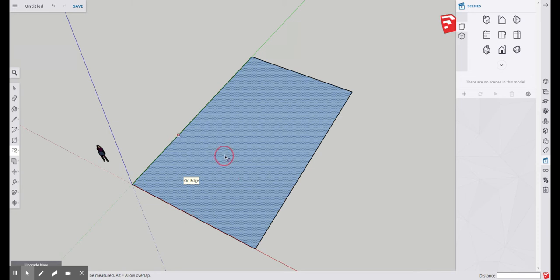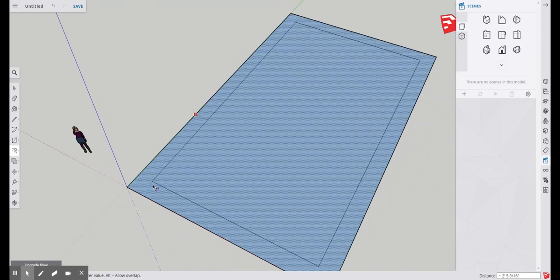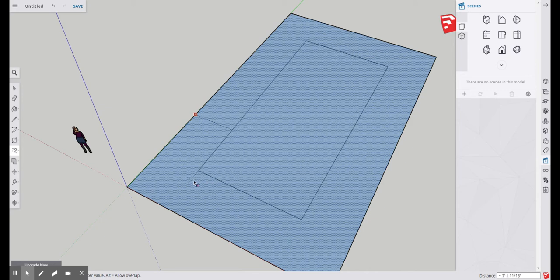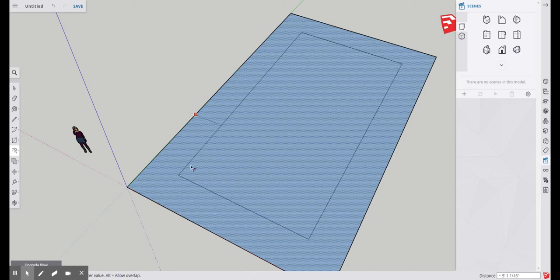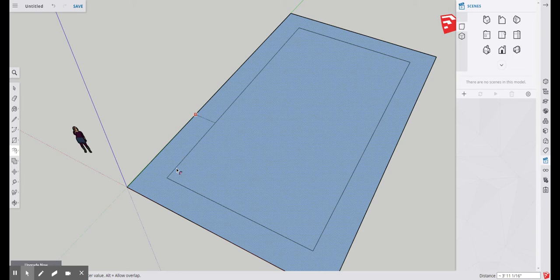So I'm going to select it, and you know, I could do all this, but I need to make sure this is inside, because if I do it outside, then our building would be bigger than 50 by 31. It would be making the exterior thickness outside when we want to make it inside. So I haven't clicked anything. Let's just make sure this little rectangle, I don't care if it's right here or right here or like right here, it just needs to be inside. And I'm just hovering. I need to type 6 feet, which is the one little tick, and I'm going to click enter.